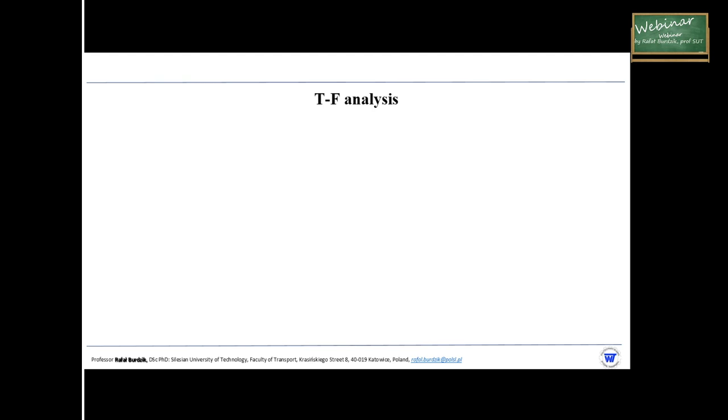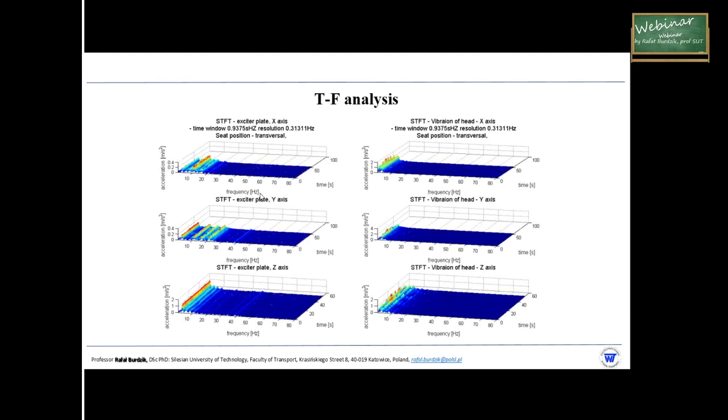According to more advanced analysis, we can also use the time frequency analysis. I presented you last time the overall understanding of the time frequency analysis, including short time Fourier transformation, wavelet transformation, and Wigner-Ville distribution. So these are results of such investigations. Here you can consider the time frequency representation of the signals of the sitting positions, for example. For the excitation plate, it is vibration of the head, so you can control the structure of the vibration.